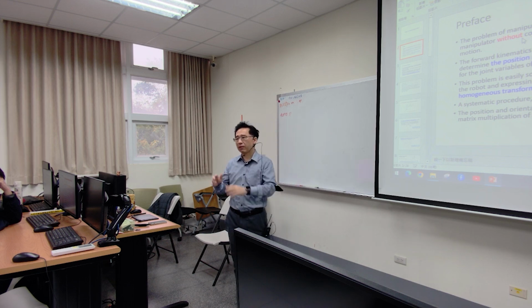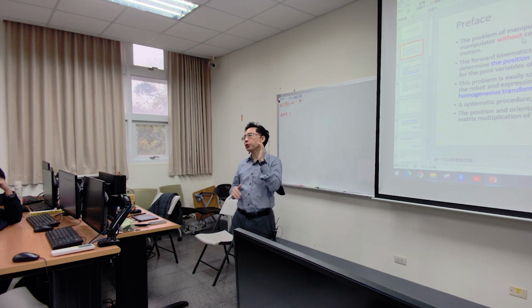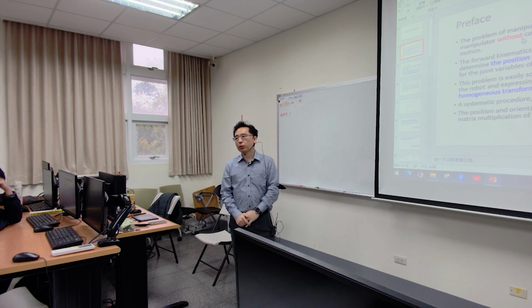Okay, so this is a convention. We call it a convention. I don't know how to translate it in Chinese. It's called DH, Denavit-Hartenberg. We can briefly call it the DH form. The DH form can reduce the original 6 parameters into 4 and can help us describe the object in space. So it's a very novel design.